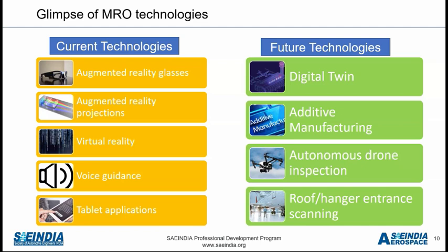But there is another thing, it depends upon the OEMs also. If the OEM has instructed the operators that you can wait for the B check also, but again it has to come from the OEMs, whether the kind of wheel materials they have used is suitable for waiting for the B checks or even A checks. So earlier they used to go definitely for A checks. Nowadays they are thinking to go for the B checks as well, because they have improved materials a lot.